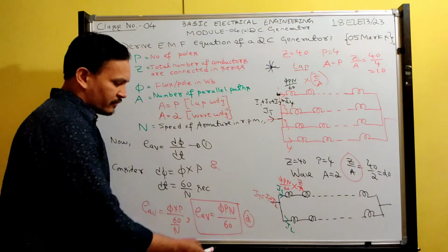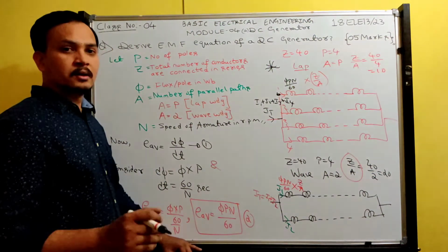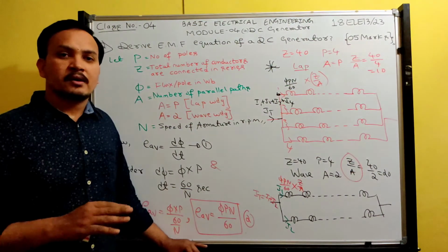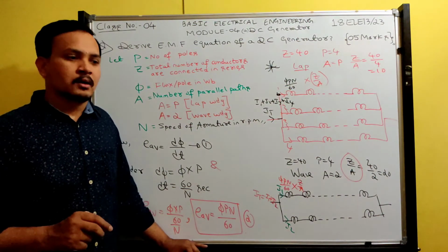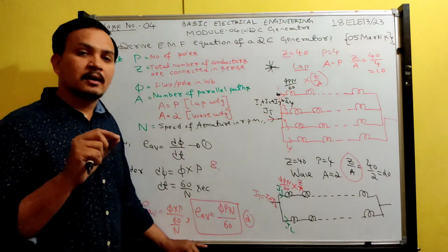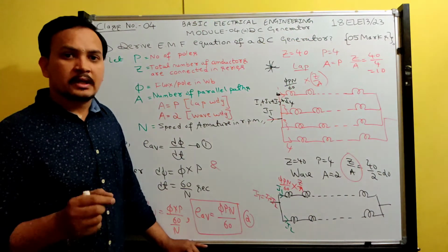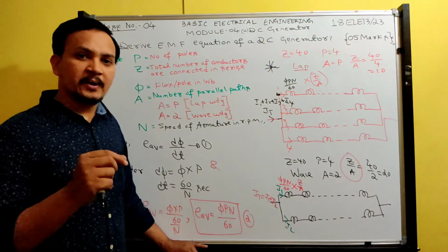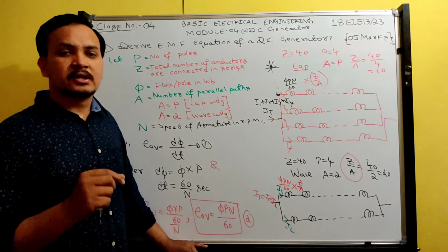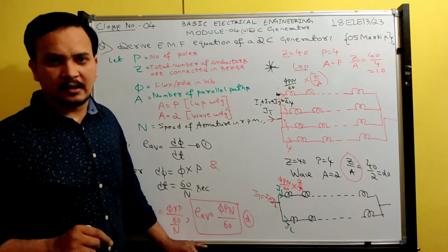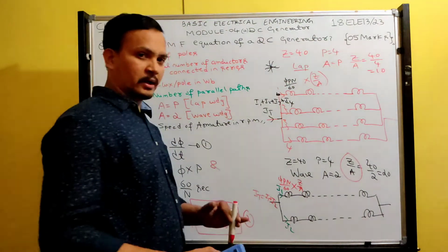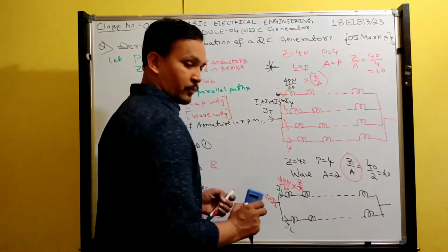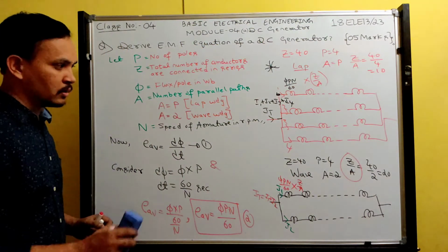See, now look at here guys. For equation 2, generally the armature winding consists of several armature conductors, and the winding may be lap or wave connected. Therefore, for equation 2, multiply by Z by A conductors, which gives the total EMF generated. Understood? That thing what I said now, you should write it here, after equation 2. So pause the video and then copy down.